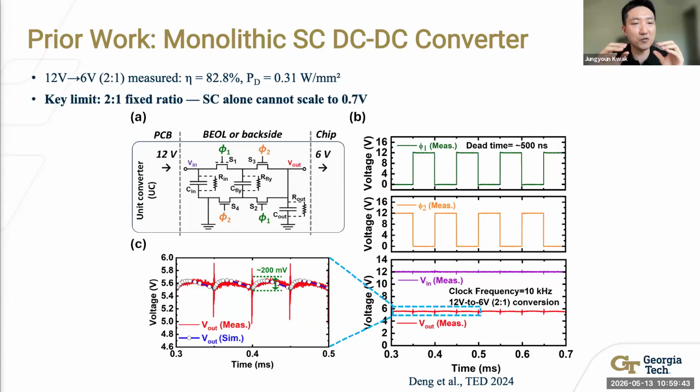Let's say you have the conventional design, and before you put in your converters, you fabricate a very good heat spreader with a high heat spreading rate. Then you put your converter on it, and they experimentally demonstrate that once you put in the good thermal conductivity layer, you can remove the heat efficiently,